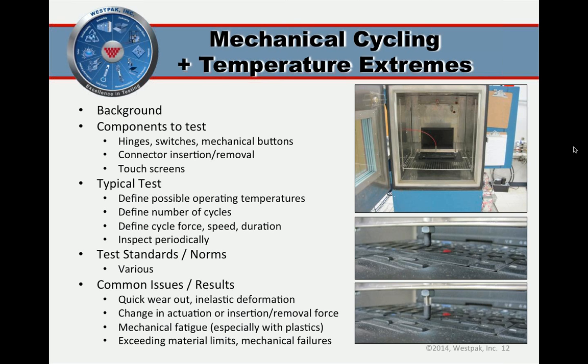So a concept here is called the click ratio or snap ratio. And the idea there is there are some mechanical ratios, if you would, of the amount of force required when you press a button to get good tactile feedback. You want a relatively high amount of force to push the button down and then have that force requirement drop about the time the button actually actuates. And those relative ratios from one to the other, the force to deflection characteristic, are very, very important. So if that changes as a function of product temperature or as a result of many product cycles pressing the button a bunch of times, that's not good. And the good news, though, is you can characterize that and test to that.